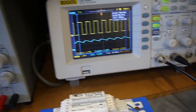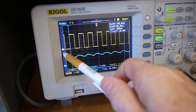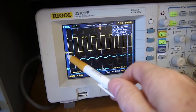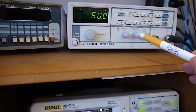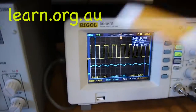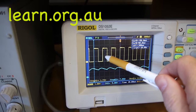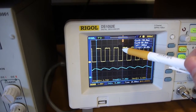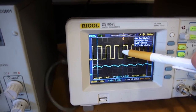Now let's examine what we've done with the oscilloscope. Channel 1 on the oscilloscope is DC coupled, and the reference is here where I'm pointing, and I've used the DC offset control on the function generator to ensure that I have a nice TTL level which starts at 0 volts and then goes positive. I didn't want that voltage coming into the base going any lower than 0.